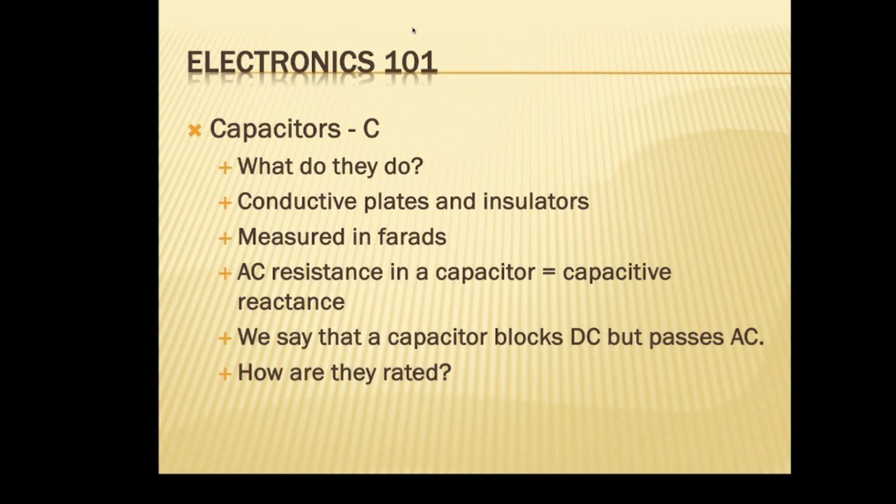That's a good answer. This is mine, because it's on capacitance, but I don't know if it actually measures one of these things. Capacitance, okay. Nanofarads. This does. Now watch out for this. Sometimes you have separate jacks here for capacitance, but that one doesn't have. Let's go to something a little smaller and see what we get there. And that one's got a minus on it, so we'll keep the minus and plus separate.